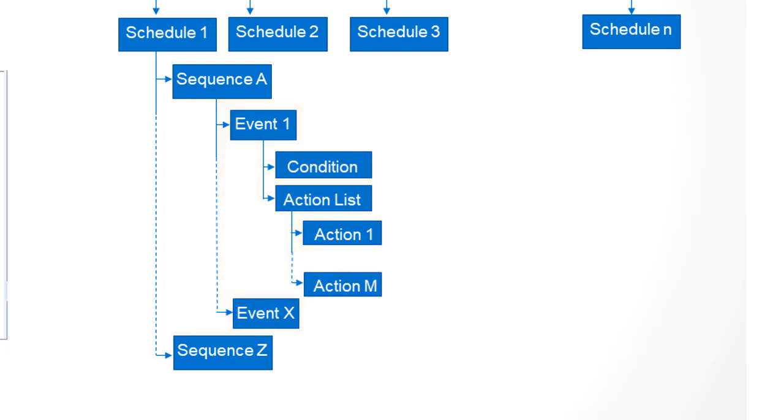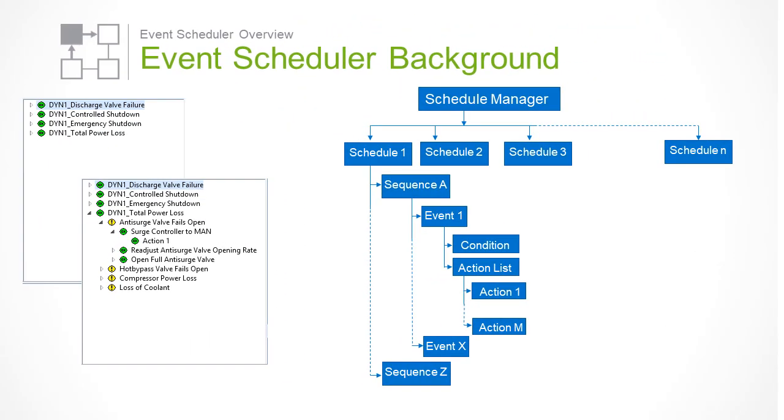If there are many series of steps to be executed, keep them within a single sequence rather than several sequences within a schedule, because the different sequences must be started and stopped manually.